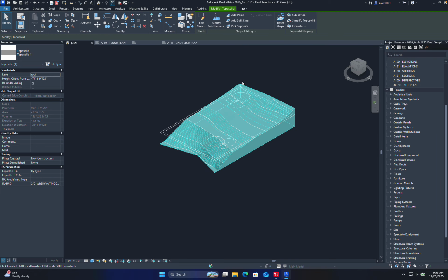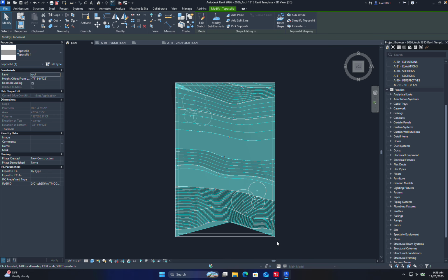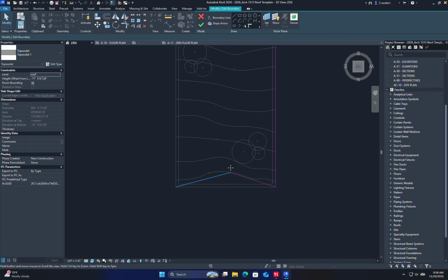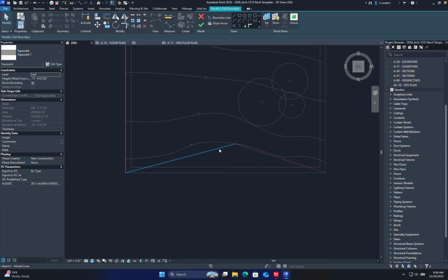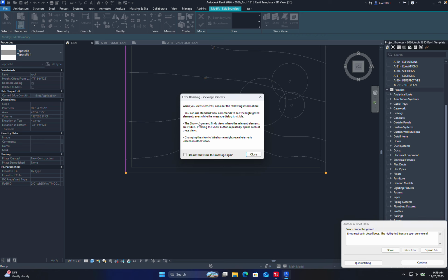If I actually want to modify the shape of this, so for instance, you may notice at the top, you're kind of missing a triangle there. You're right. If I double click on that, because it basically defaulted, I'm going to go ahead and not remove these two lines. I mean, don't get me wrong, watch this. If I remove these two lines and I try to accept it, it's going to go, hey, hold on, buddy. You've actually got these disconnected points. So Revit is trying to help you, and the emphasis is on trying. It's arguably sometimes not helping you, right? Sometimes it'll literally say, I don't know, right? And in fact, you'll click on show me. Hey, show me the error here. And it literally goes, hey, I can't show you.